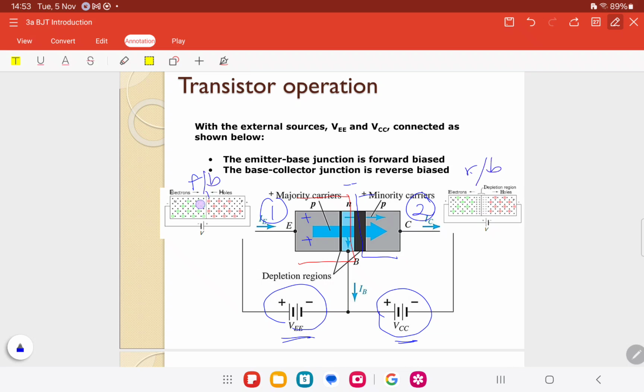How to determine? Look at the depletion region. For forward bias, there is almost no depletion region, there is no difference in the middle. For reverse bias, it has a wider region in the middle. Most of that is the effect from the external electric field that we apply.